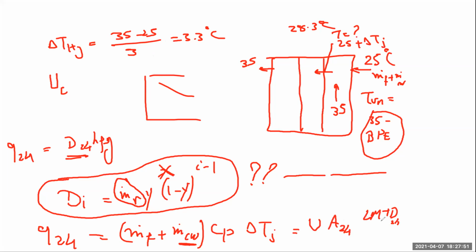So we are going to make an energy balance around the whole plant as one control volume, calculate the value of m dot cooling water, and then calculate how much Q has been heated by the vapor that's condensing on the outside surface of the tubes. That would make more sense to do.